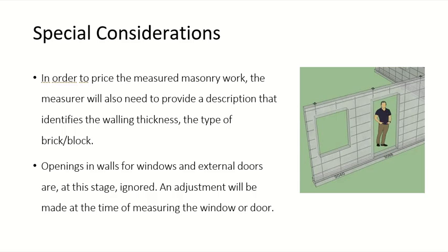This I already mentioned. Yeah, openings. So you have a wall, this wall, right? This wall has windows in it. This wall has a door in it. When you calculate the quantity initially, you will take it complete, including everything, like there is no wall, no windows. Nobody will come in, nobody will get out.